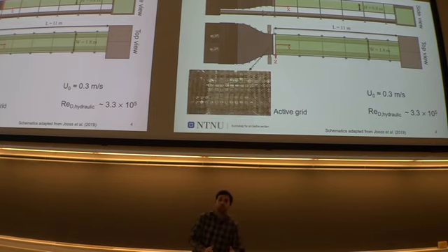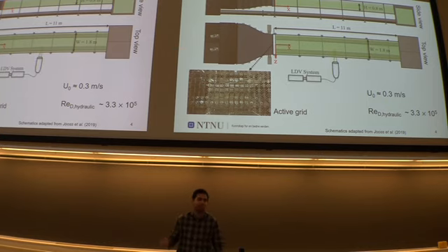And this is what you use to actually generate the shear and the turbulence. It's an active grid. It's basically a bunch of wings that you can turn on rods. If you turn them in the right patterns, you can make shear, you can make turbulence. You can make lots of things. And of course, it's not enough to just make the shear. You need to measure it as well. So I used LDV. LDV is a laser technique to measure flow velocity. I won't go too deep into that, but the main point is that it's non-intrusive, so it doesn't affect the flow.